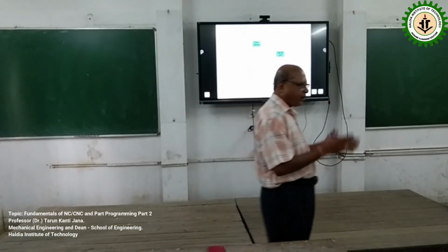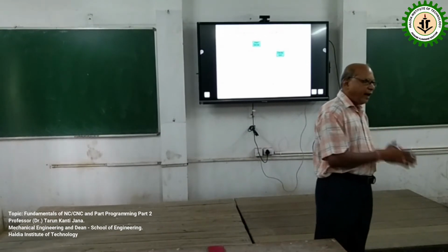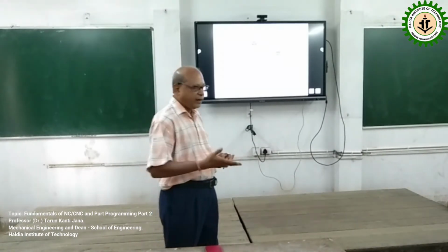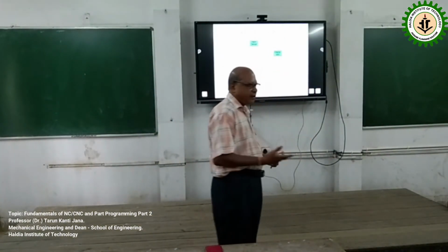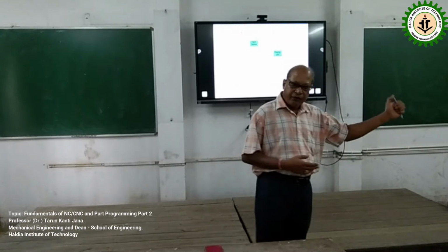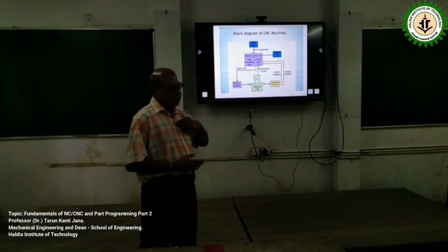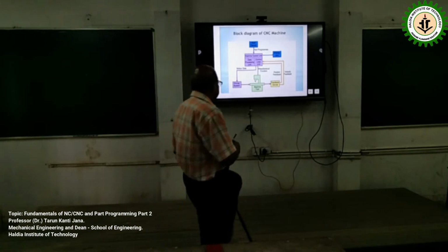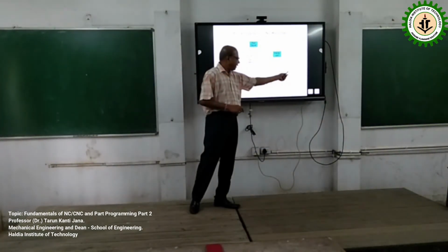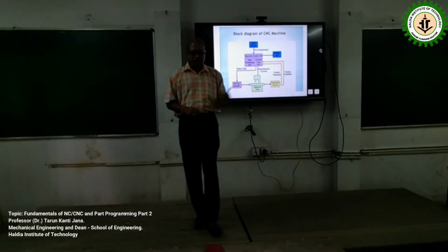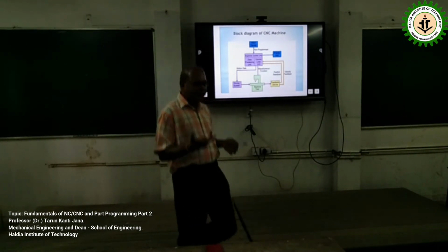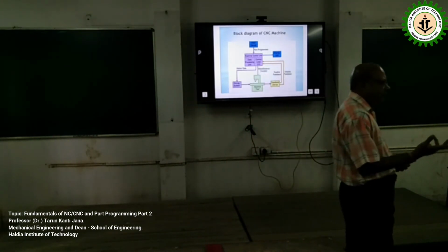Okay. So the monitoring of the speed of movement and the exact specified displacement both are required to be observed or monitored, and corrective actions taken automatically and continuously, so that eventually the slide will move up to the desired distance following the defined speed. For this purpose, two different transducers are required. One is called the position feedback device, another is called velocity feedback. Velocity feedback is normally taken care of by the tacho generator, and position feedback may be a linear scale based on a fringe pattern. Another popular device is the encoder.